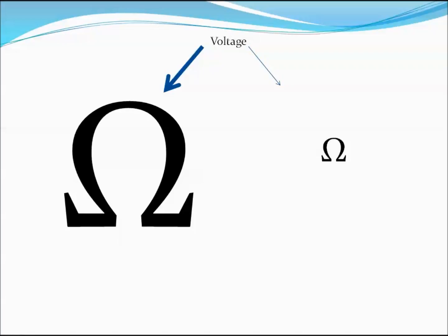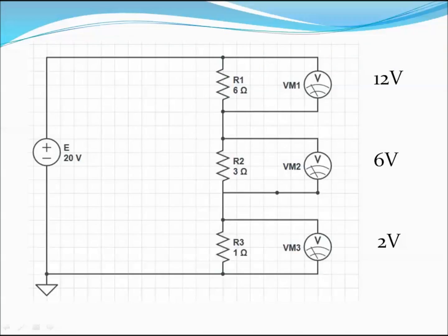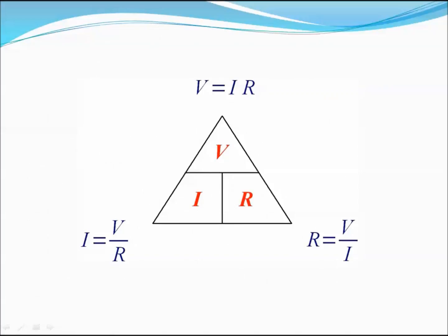As you can see in this simple circuit, the largest resistor captures the bulk of the applied voltage, while the smallest resistor has the least. And the ratios of R3 and R1 are 6 times larger in both resistance and voltages. To find the voltage and resistance of each, you'll first need to calculate total current, and then use Ohm's law to calculate the voltage over each resistor.